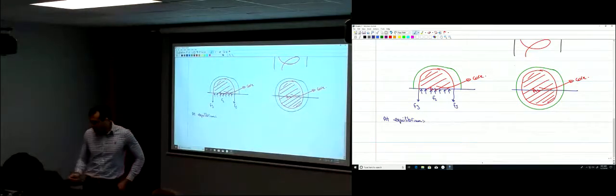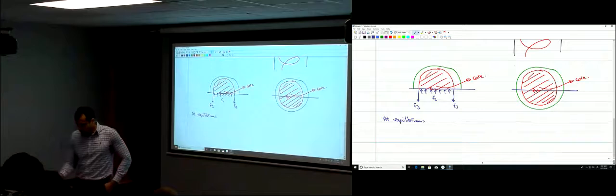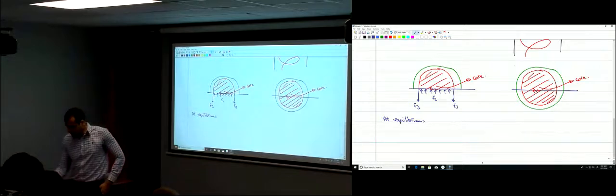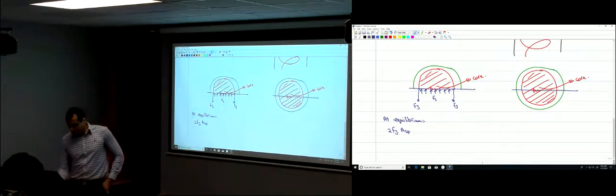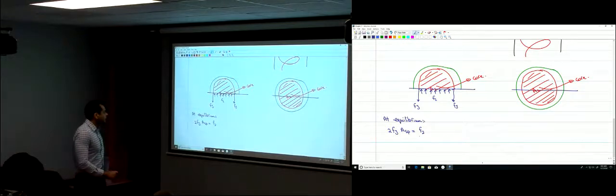So how much is the force in the spirals then? You have 1 here and 1 here, so you have 2 F yield multiplied by the area of the spiral, and that is equal to the force generated in the core of the concrete, which is the stress F2, multiplied by the area over which this F2 is applied.